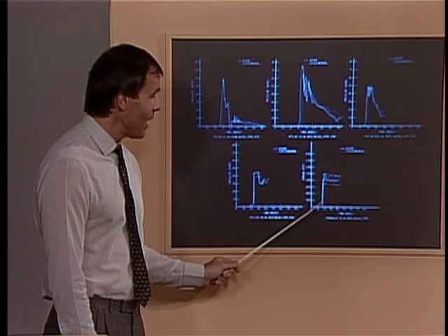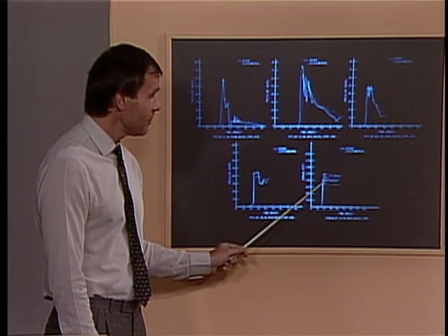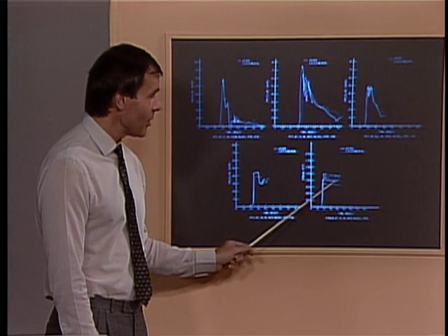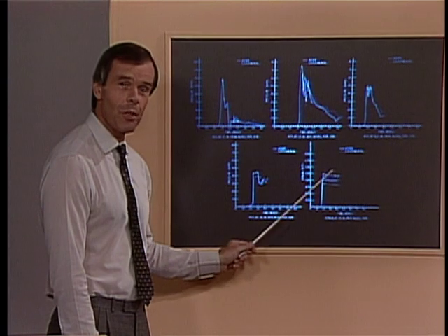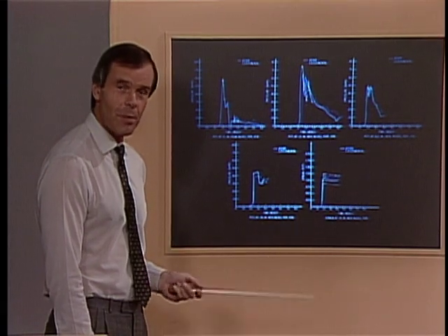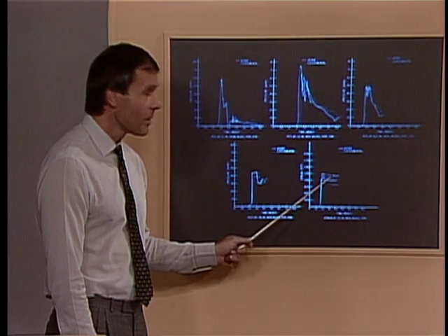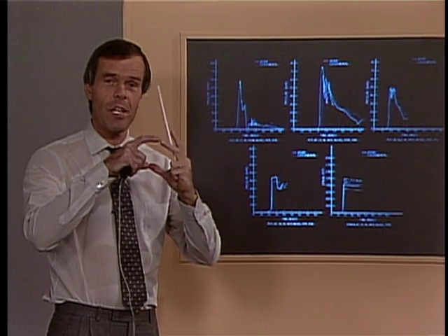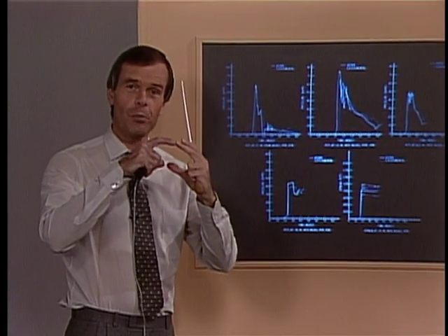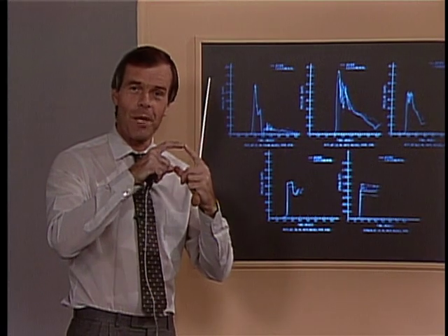Notice that here finally we compare the hoop stress predicted by ADINA with the experimentally observed hoop stress as a function of time at one of the stations within the pipe. Notice that for the hoop stress here we have 4 experimental results corresponding to the measurements that were taken at the North Pole, the South Pole, East Pole and West Pole on the pipe.